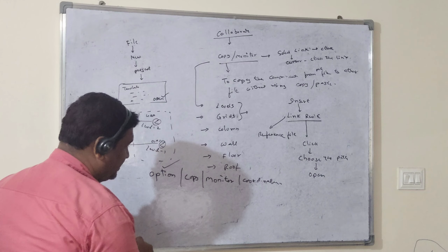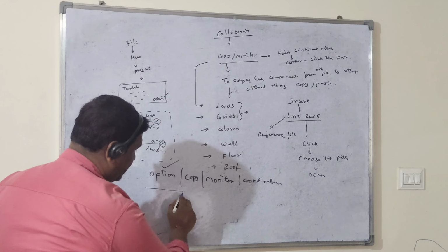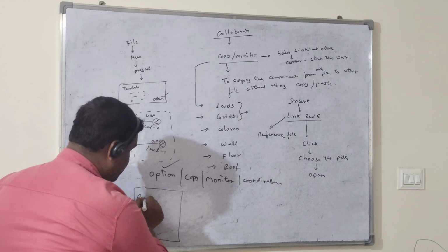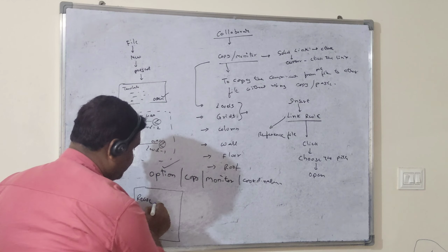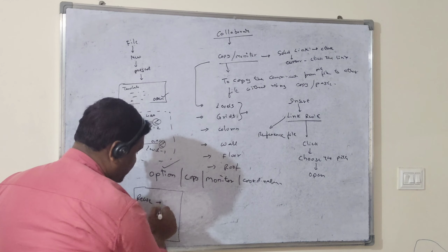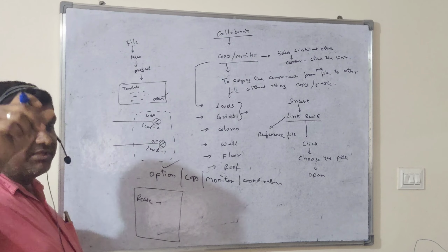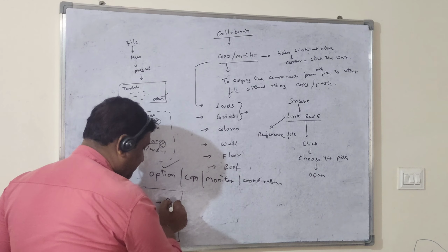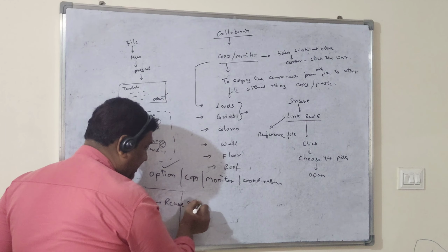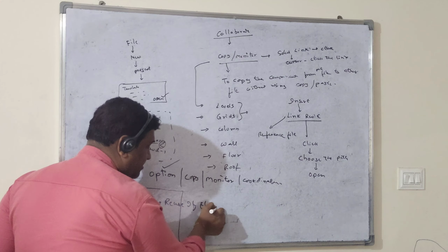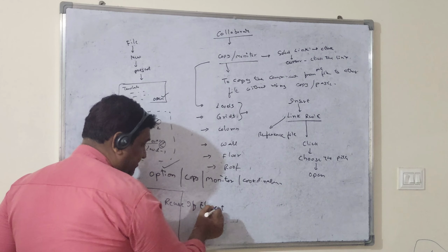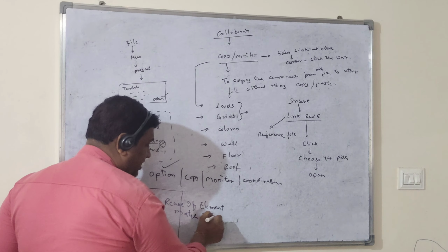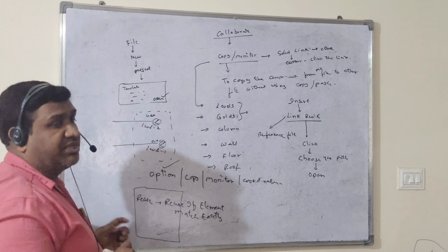After clicking the first option, there is one palette that appears. In that palette there is an option, reuse. There is an option in the palette, reuse. So in that option reuse, there is a drop menu. There are 3 types of drop menu. So in those 3 types of drop menu, you have to select the menu reuse if element match exactly. This menu you have to take. Reuse if element match exactly. You have to select that menu in the reuse option.